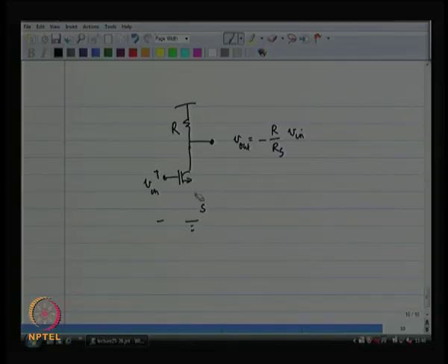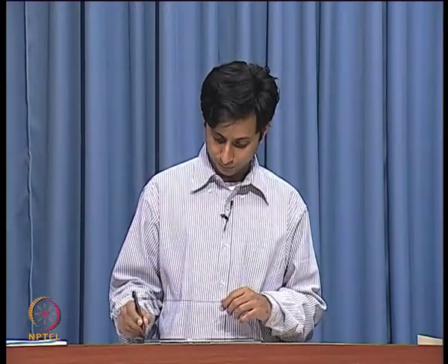You can easily conceive of this, and here this is irrespective of whether the input signal is a large signal or a small signal. This is the way we linearize. Now, you could also conceive of putting an inductor over there instead of a resistor. Even that is going to help you in terms of linearization. So, at DC there is going to be nothing, but at the high frequency that will present an impedance, and at that high frequency this is going to behave like a perfectly linear amplifier. So, this is the technique we are going to use.